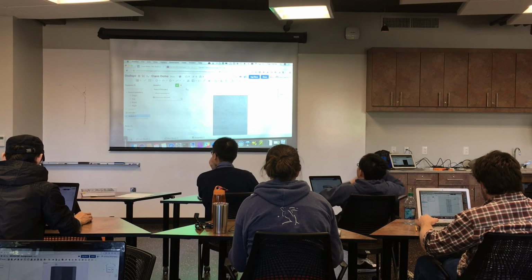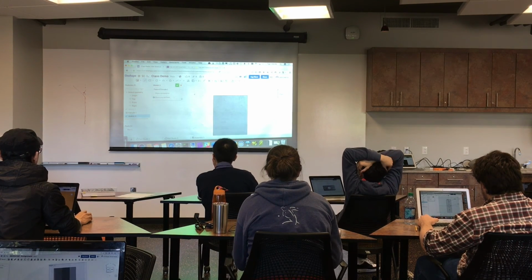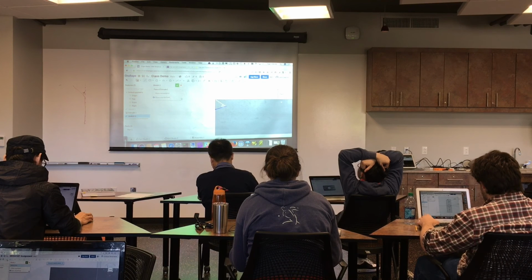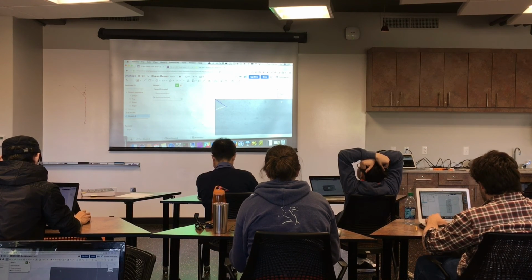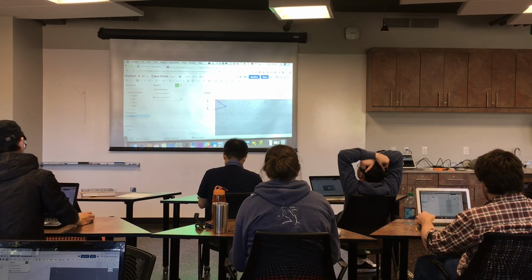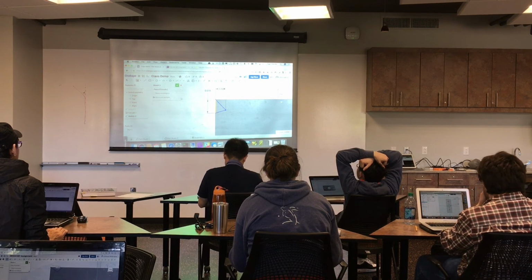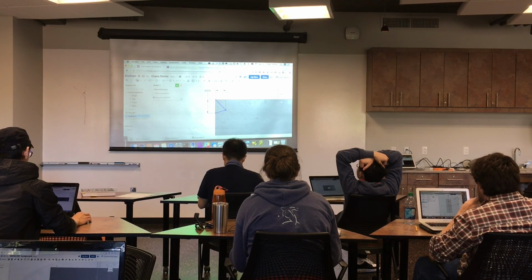I'm going to zoom in up here, and I'm going to draw a triangle with lines. I'm going to click the corner, click here, and click back there. So now I have a nice little triangle. I'm going to go ahead and dimension that. Here, I want it to be 1 millimeter. From there to there, I want it to be 0.8 millimeters.